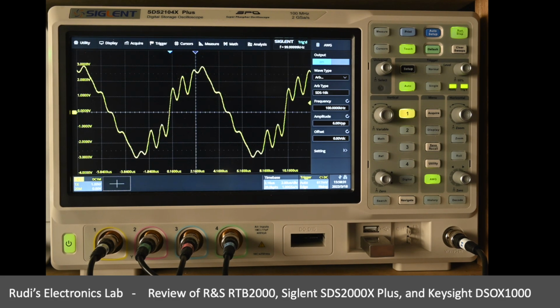So I spent quite a bit of time trying to work with EasyWave. I am able to transfer something from the scope to EasyWave, but the other way around, EasyWave recognized the oscilloscope. I can see the oscilloscope number coming in properly. It asks me in which of 1 out of 4 slots I want to save something. I hear some relay switching and that's it. The file is not in the oscilloscope at all.